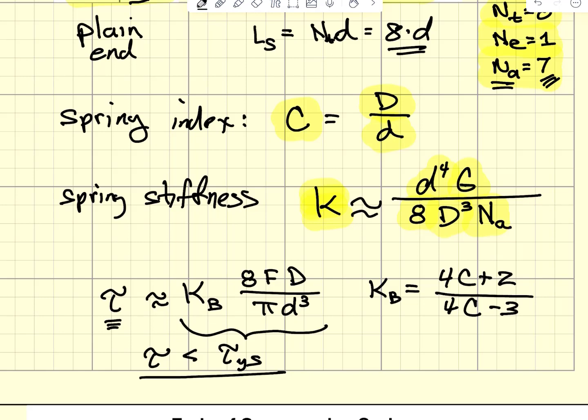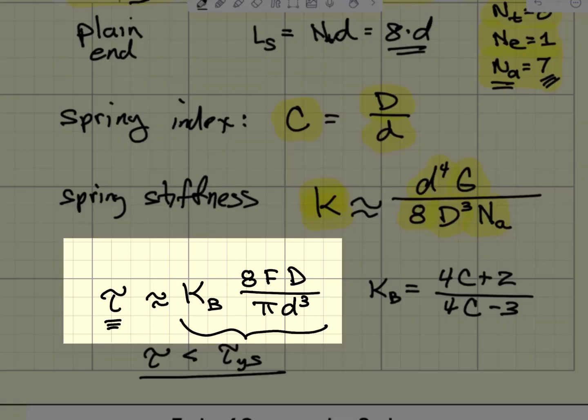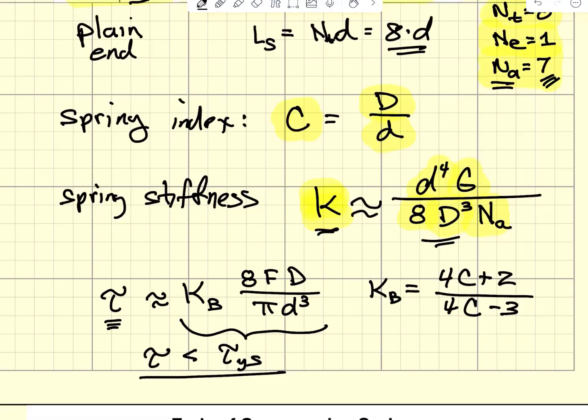In a previous lecture, I showed you that you are not always going to get really good agreement between the Castigliano estimate and an actual measured value, either through direct spring compression or a value measured using finite element analysis. So this K is important because we're going to choose a spring stiffness to give us a load displacement relationship that is suitable for the mechanical application that we're going to be using.